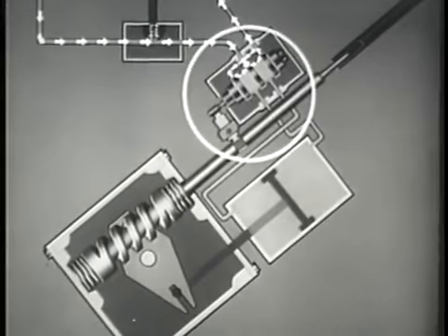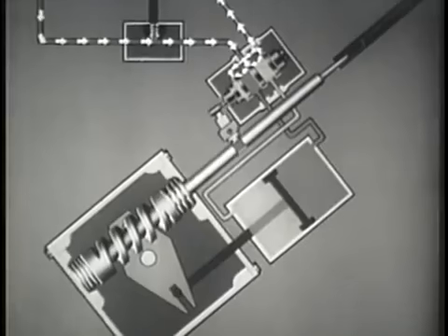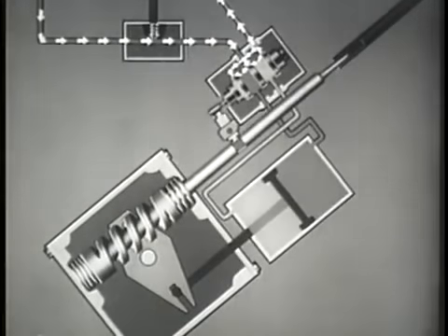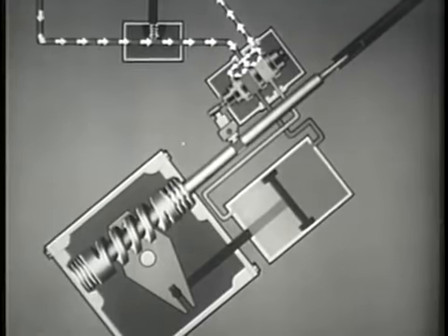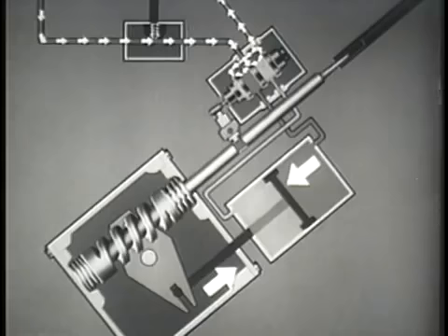The movement of the cam actuates a control valve, which in turn directs increased pressure to one side of the piston. This increased pressure will be equal to the shock received by the front wheel, causing the front wheels to remain in a straight-ahead position.